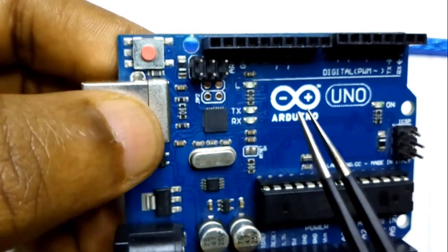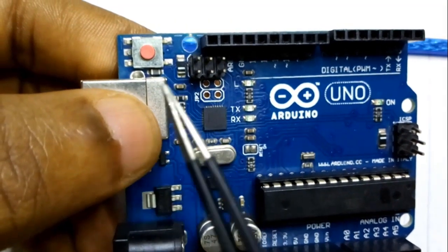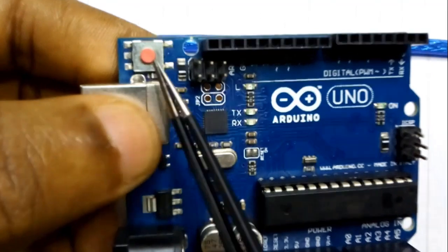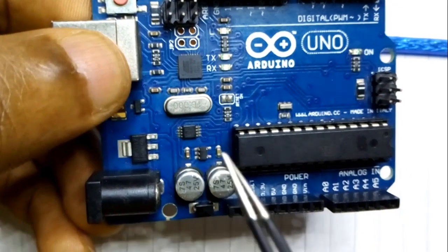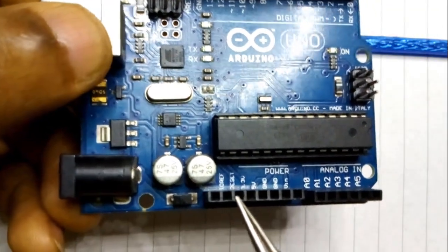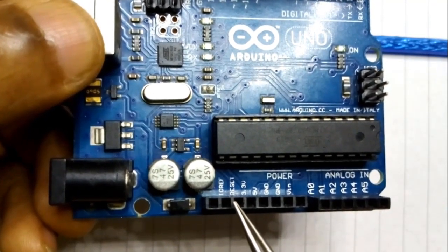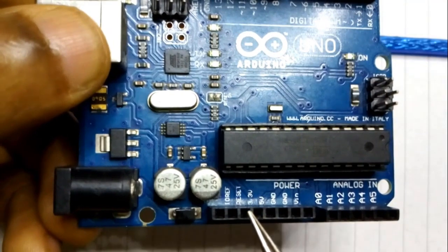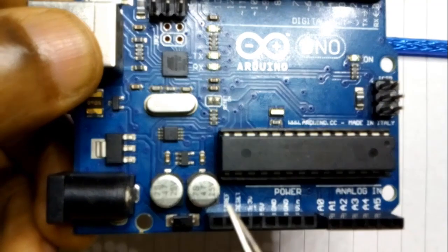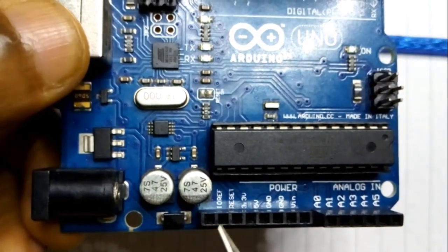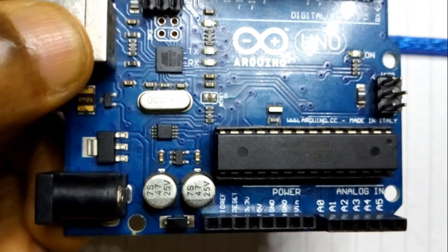You see that if you embed this Arduino into a project, then it wouldn't be convenient to be opening the project to press this reset button when you want to do such a thing. So by extending or breaking out that reset functionality on the pin, it gives you the ability to interface your own push button to control it manually or externally. The reset pin is an active low pin. What I mean by active low pin is that it is activated on a low signal.